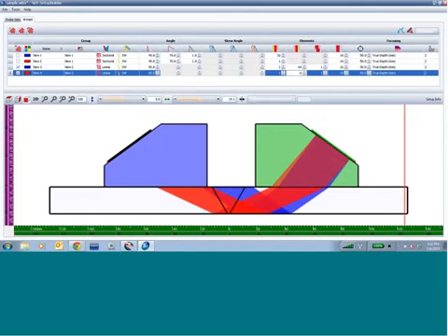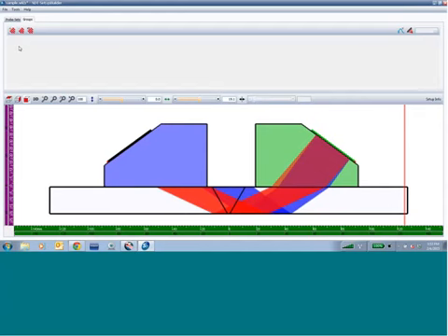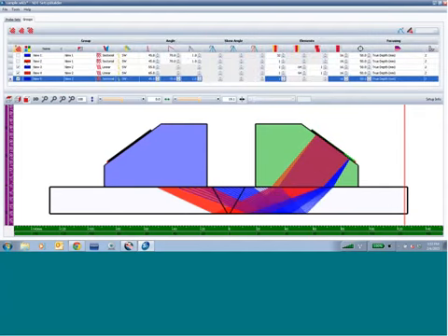So what I'm doing is adding a secondary linear scan to try and get the coverage of the root, making sure that the bottom part of the bevel that I was covering was correct, but now I end up being short with my heat affected zone at the top. So if I wanted to cover this simple single V joint with linear scans, I end up adding 3 separate linear scans, each one at different angles, to get that coverage. So now I have the top, the bottom, the bevel, and the root covered again. A little more complicated, a little bit harder to do with linear scans.